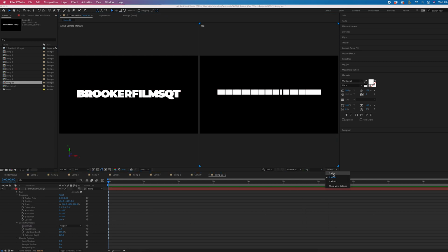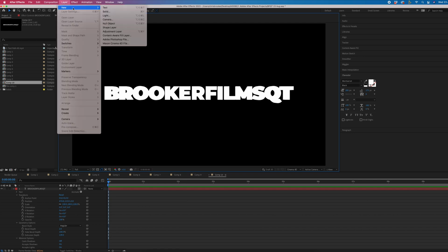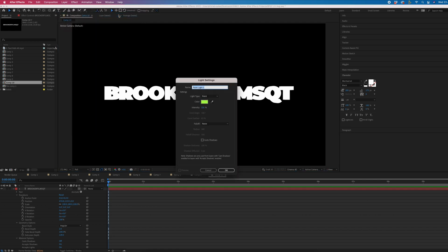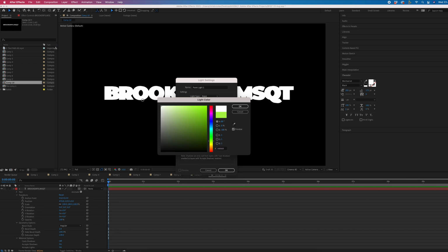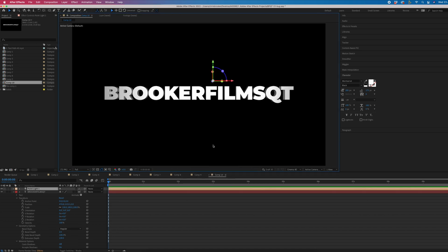So we'll go out of 2 views and go to 1 view again. But the problem is there is no lighting here. We can't see the 3D effect in place. So we'll go to layer, new, light. We'll change the color of this to white. You can change the light type as well if you wanted to. So parallel, spot, point, ambient. I'm just going to go for point. We'll press OK. And you can see that's created some shadows on the text.